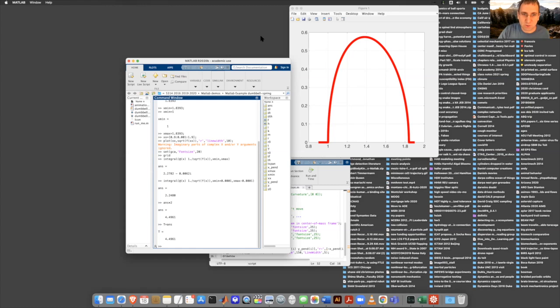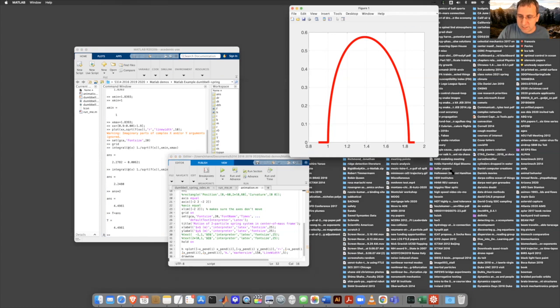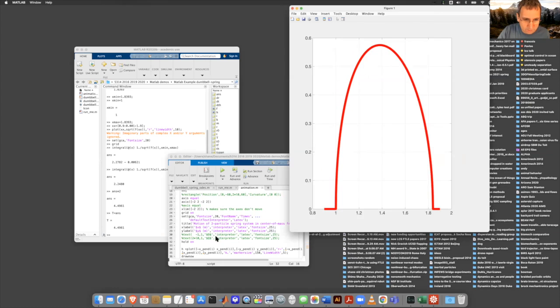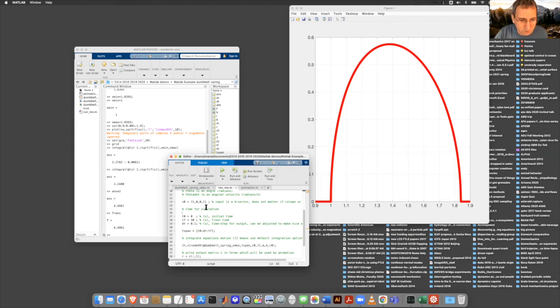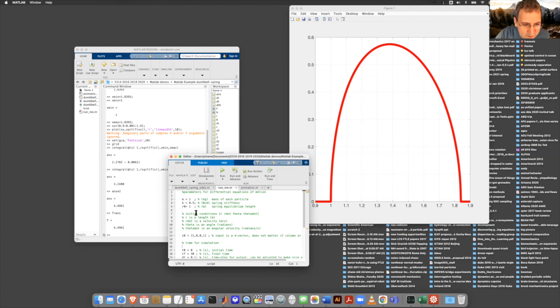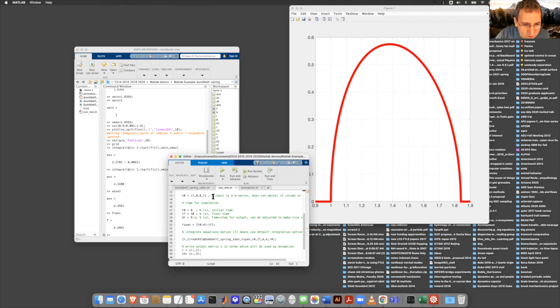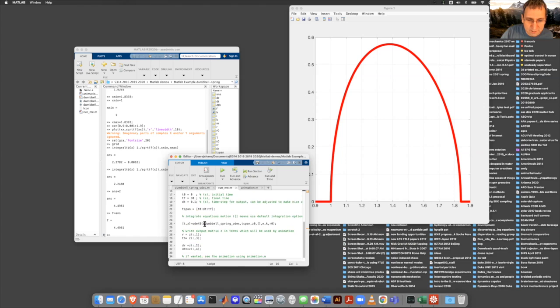If you want to see what the actual motion looks like, the details of this aren't important right now, but I was able to write the Newton's laws and then the second order ODEs. You turn them into first order ODEs. I'll probably go through this more carefully at some other point. I've put in the parameters that I just wrote, and then initial conditions. There's 4, right? Initial R, initial theta, initial R dot, initial theta dot. I'll have this go from 0 to 30 seconds with outputting every 0.1 seconds. And then there's ODE45, dumbbell spring ODEs. Just run this.